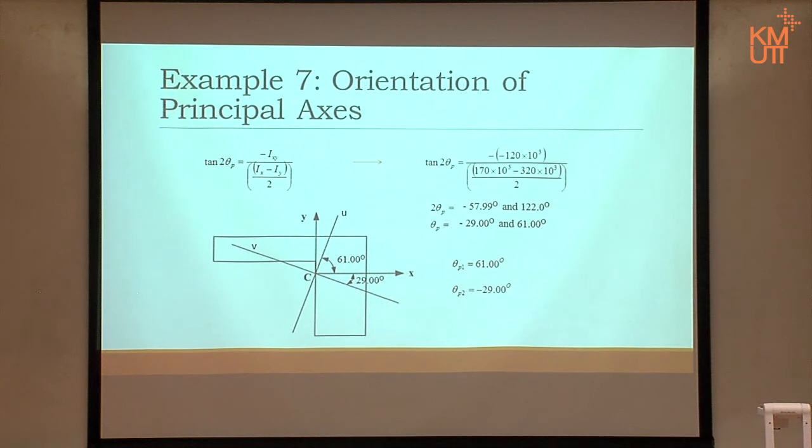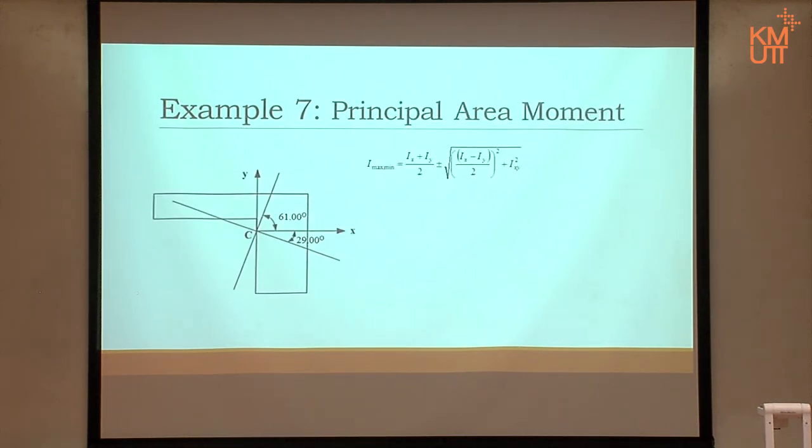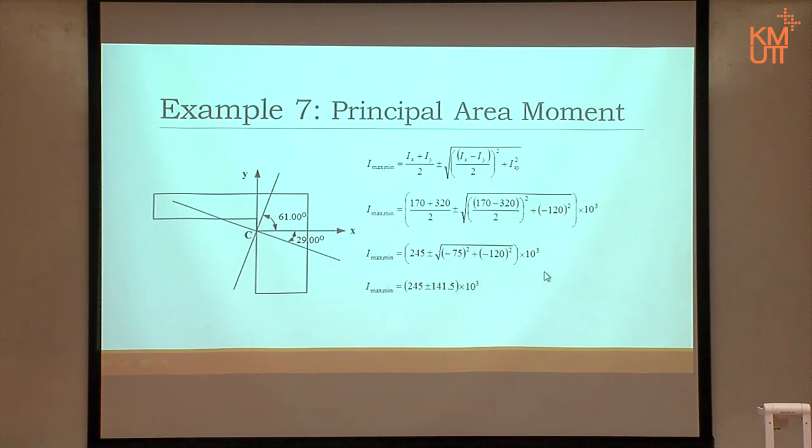Right? Just draw. It said draw the orientation. You just turn it according to what it is. Right? Then you want to find Imax, Imin? We have the equation. What are you afraid of? Here, equation. We know Ix, we know Iy, we know Ixy. What to do? Substitute for it. There, the plus is max, the minus is min. Separate it out. What's the problem? It can't be any easier.